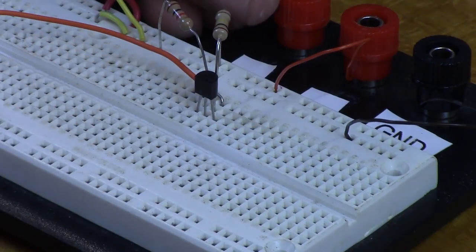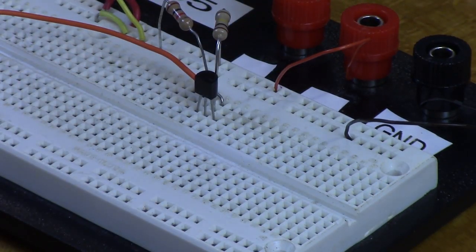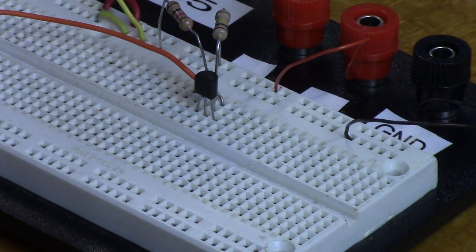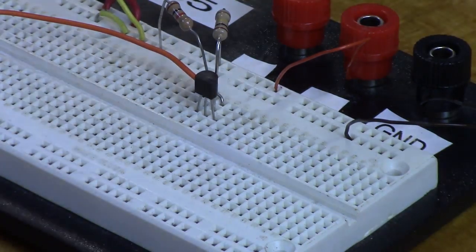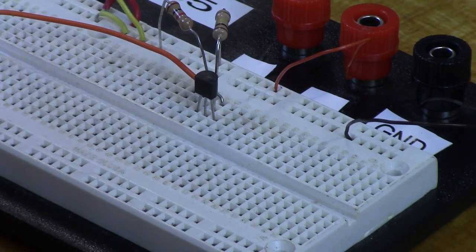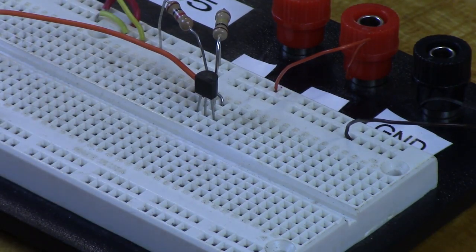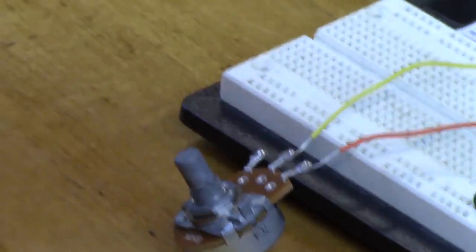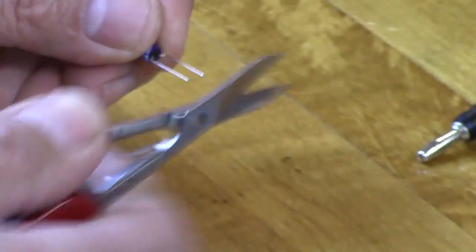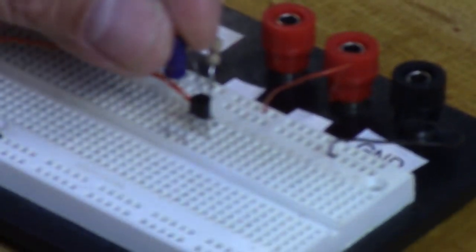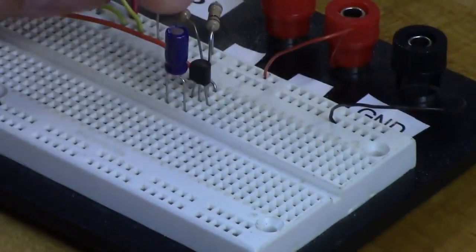Okay. And now we're also going to have, going to the base, Vin. So we're going to have our input capacitor C1. Now I'm switching to a 10 microfarad capacitor because I saw some bandwidth issues with the 1 microfarad capacitors. So I got 10 microfarad capacitors. These capacitors are electrolytic, which means that they have a plus and minus side. They are polarized. So I'm going to plug in the plus side pointing toward the base because that has the higher DC voltage, like so.